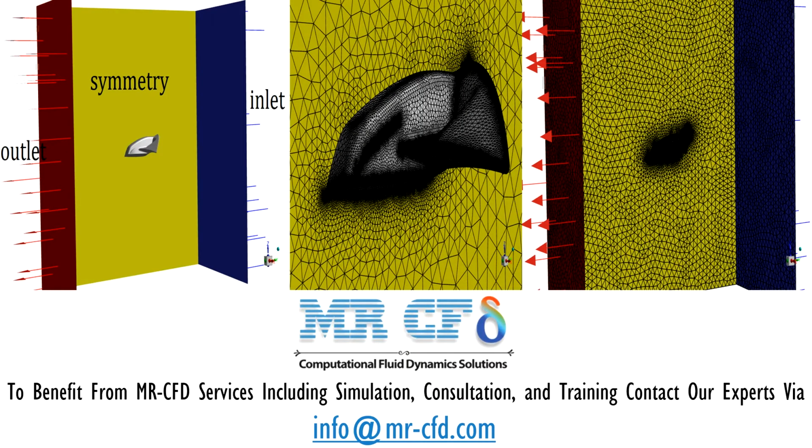The geometry of this project is designed in ANSYS Design Modeler. ANSYS meshing software also has been used to create a computational grid and mesh for the geometry. Also, due to the sensitivity of changes in important components of the flow, such as velocity and pressure near the boundary of the two fluids, and also where the two phases collide with the body of the jet ski, we have tried to use finer and better grids and meshes. The mesh type used in this geometry is unstructured.